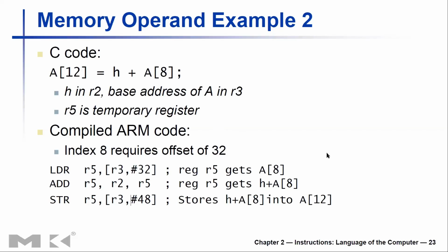That's a good question. It's good that you noticed it. If you have that idea in your mind, then you will place the arguments in the proper places when you are using LDR and STR. You should put the destination here when using LDR, and you should put the destination here when using STR. So that idea you need to have.